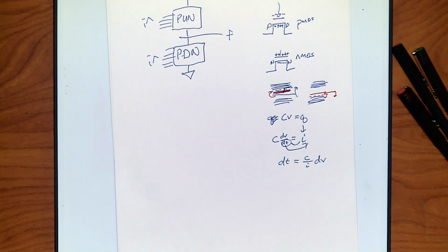Okay? So in general, I have to make my capacitor larger for PMOS gates to get the same speed across them, so I have the same number of charge carriers because they have this longer route to become available. In general, it's about 1/3 the speed that they're traveling at, which means I need them to be about 3 times as big. That's a huge increase. So you think for similar sizes of these, my PMOS network is going to be 75%. That's huge, right? But here's the problem.